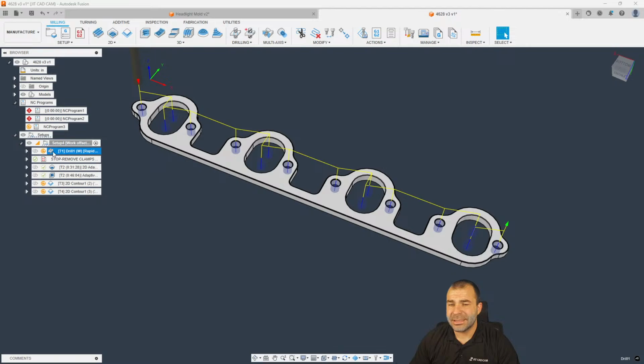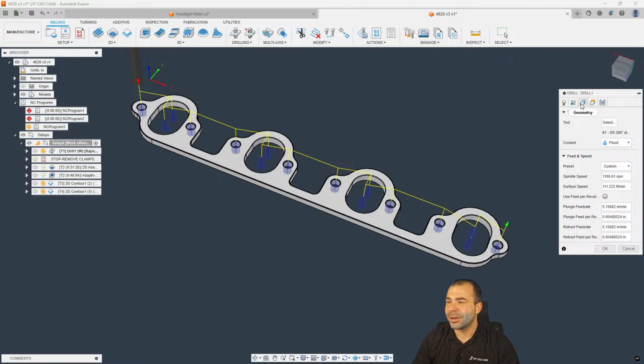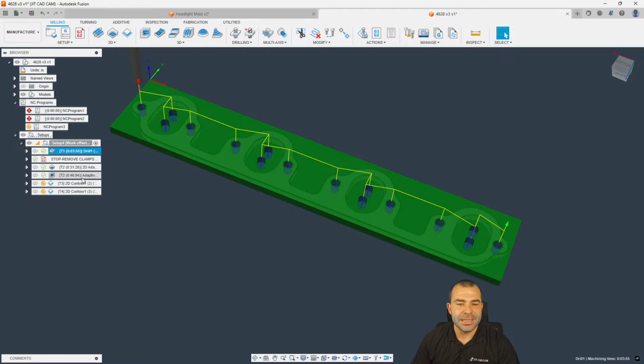And now on the drilling side of things, we did already set that first one. Because we did a pattern, we get that error because we are lacking one of those faces, right? So keep in mind those other 3 ports have all changed to the first one. So we only have 2 faces, the through hole and the center drilling on the corner, allowing everything to happen automatically. So Wes, I hope this helps a ton.